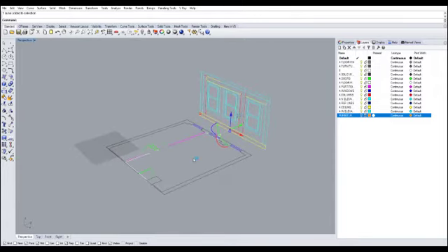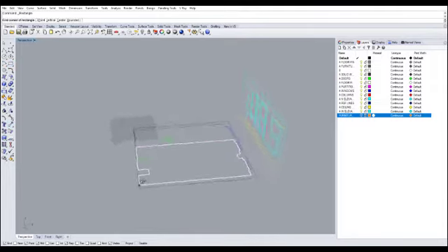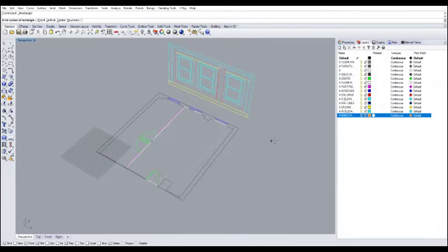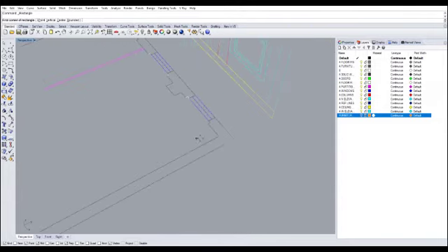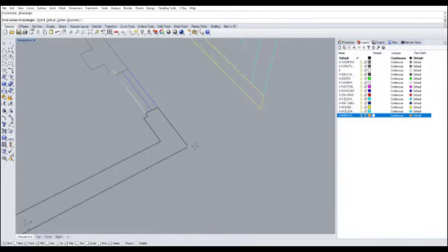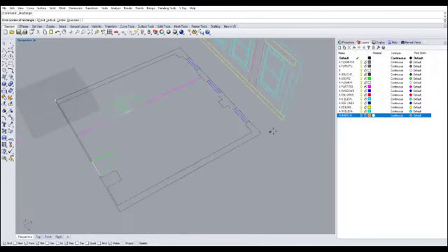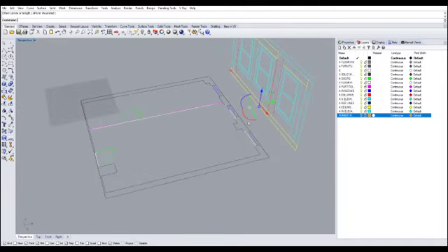So to draw in Rhino, it's actually quite no different than in AutoCAD. There are various drawing tools, including a polyline, regular line, circle, and so forth. So to draw a floor, which is a perfect rectangle, let's choose the rectangle draw tool. Just like in AutoCAD, it's left click to start, and drag to where you want to finish the drawing. So let's left click here to start at one corner of the rectangle, and then drag to end here where we want the floor dimension to be. So again, left click here, drag, and left click once again to finish that dimension.